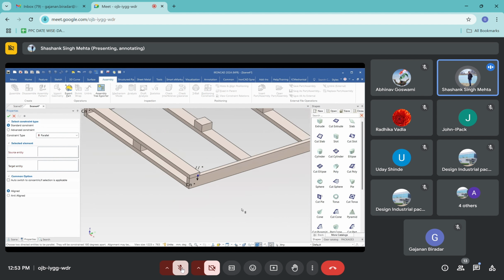The frame pattern, right? So this is the frame pattern. The number of patterns should divide our assembly overall length, OL. So it should be divided by that particular length. So we just need to provide this expression like overall patterning. OL is showing the overall length of our pattern, and OL divided by the distance, right? So the distance which you need to provide, we have provided as the value. It should apply. Okay.